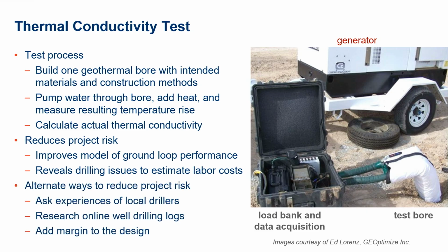There are other ways to reduce project risk, such as leaning on the experience of local drillers, using online well drilling logs, or adding design margin to the project schedule and budget. But given the cost of installing a geothermal system, our suggestion is just to do the thermal conductivity test.